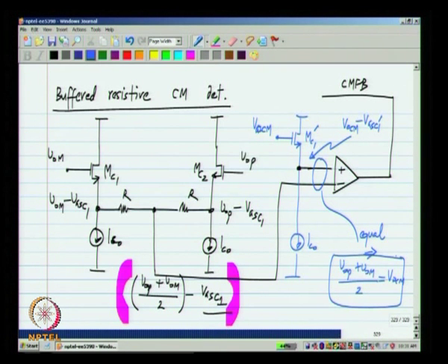Now, this business of exploiting matching on integrated circuits is very common. We have used it for simple circuits like current mirrors. There are so many cases where you have two things to match very well, you have to match all the parameters. In that case, you simply use a replica circuit. Now, that sounds vague. I have shown you one instance of it. So, whenever you have, let us say, voltage drops or some other parameters dependent on MOS transistor characteristics, you may be able to use a replica circuit, so that the dependence on MOS parameters, which is also process dependent, will be cancelled out.